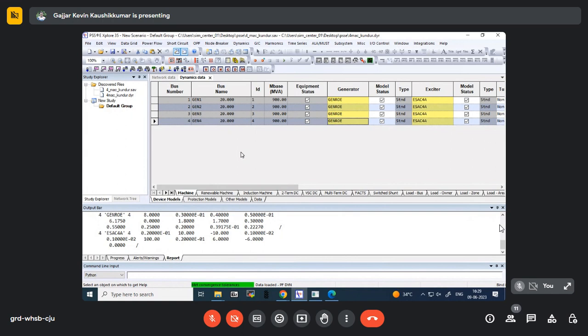So one good feature of PSSe is that PSSe is fully integrated with Python. What I'm trying to say is that if you have Python installed, then just by using Python, you can use all the functionality of PSSe just by command line. So you can write a program, just save it, and just by changing parameters there, or making a loop or any kind of logic you can build there, run multiple programs or multiple routines in PSSe using Python.